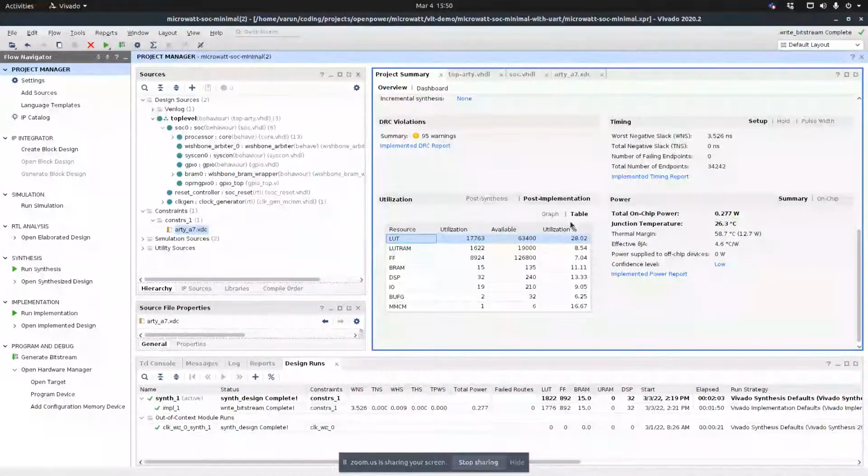If I may, yes, there is Symbiflow. You can actually use it. It does install, but the thing that I found is that if you have very large adders over 128-bit, over 95-bit, which in the divide unit of Microwatt there is, you must use the no-carry option.